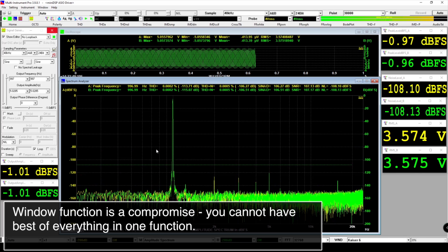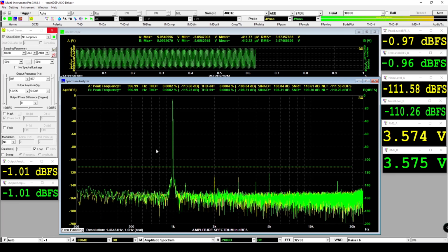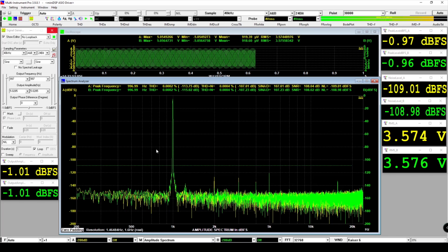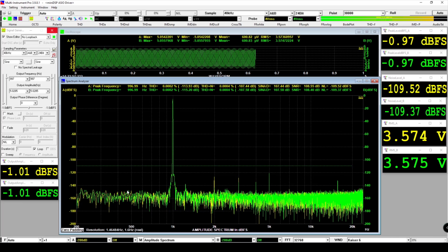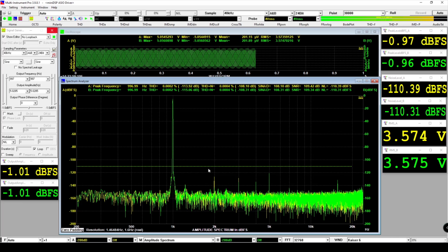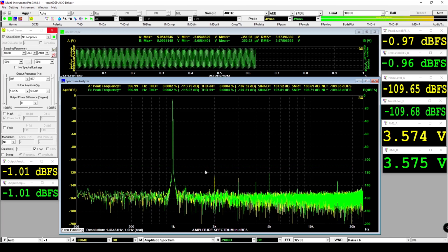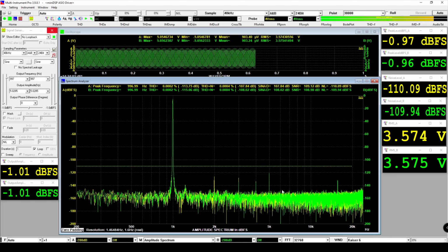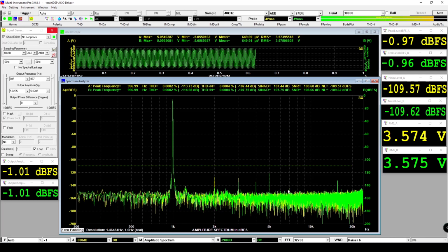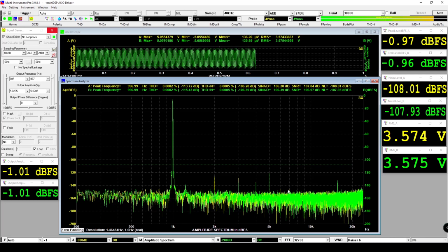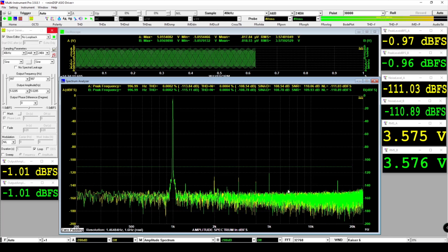Luckily, when we do this kind of audio measurements, I think our needs are fairly basic in a way. Okay, we want to push the noise floor down, but our tones are not very close to one another. The harmonics are quite widely apart. Okay, if you do some modulation measurements, then your tones may be close to one another and you need to take that into account. FFT really is the most useful representation of any signal because it tells us so much